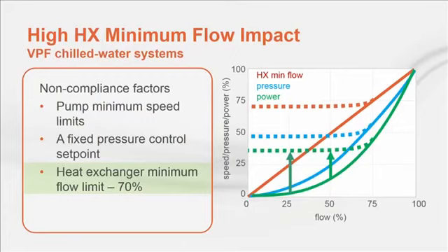This magnitude of difference is not uncommon or extreme in non-compliant systems. So while the Affinity laws do predict the ideal performance of dynamic compression devices in frictional flow loss systems, there are many more HVAC systems that don't comply with these operating principles.